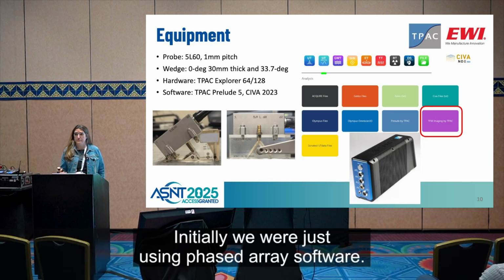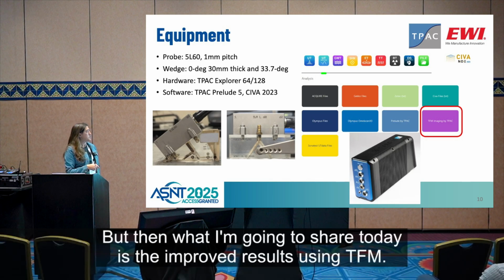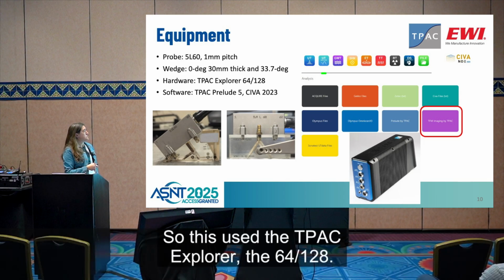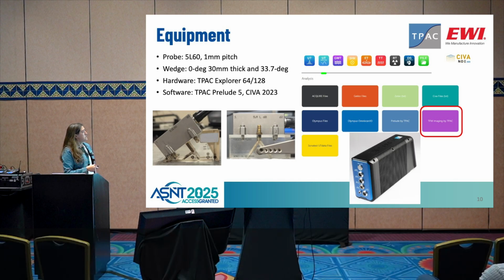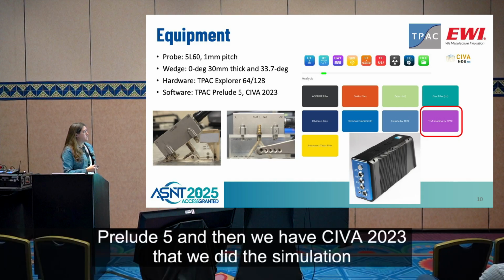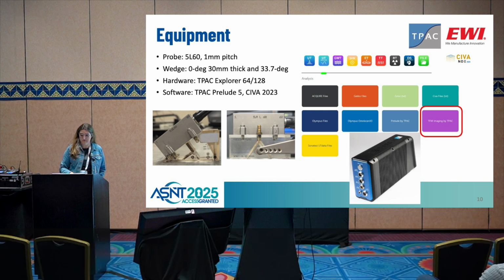Initially, we were just using phased array software, but what I'm going to share today is the improved results using TFM. So this used the TPAC Explorer, the 64/128, so we could use all the elements in the probe. Prelude 5, and then we have CIVA 2023 that we did the simulation and reconstruction in.